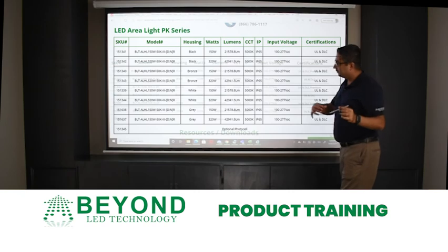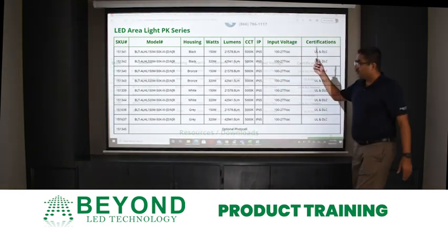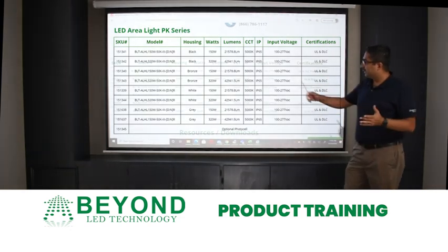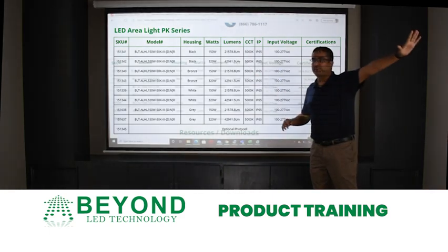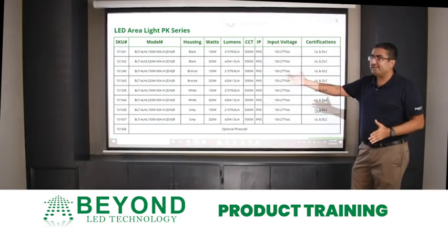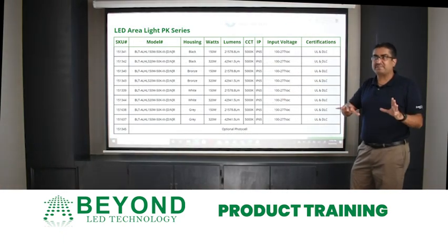Now let me recap. We started with wattage and voltage, the difference between wattage and voltage, and the lumen efficiency going from 70 lumens per watt about 5 years ago to 170, 180 lumens per watt now. We talked about the UL certification, which is safety certification.